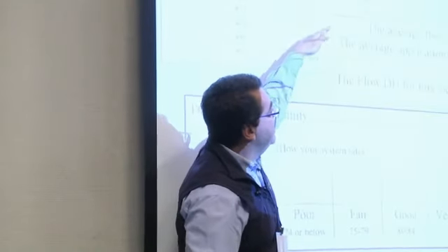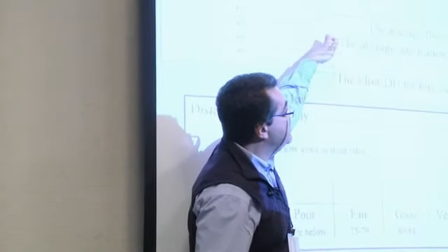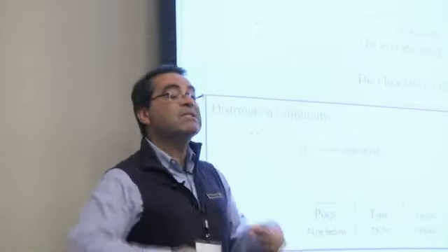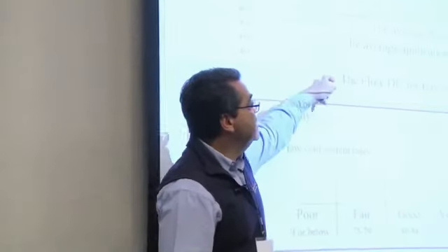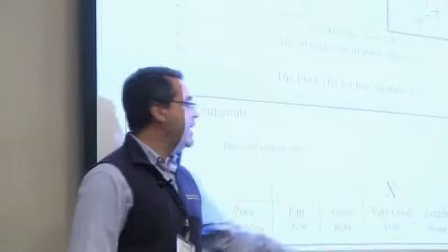You get the average flow rate of the emitters they measure, the average application rate, how many inches per hour your system really applies, and this is the DU, and then they score your system based on certain categories. In that case, it was performing very well. But you also get other information that can give you an idea where the problems are.